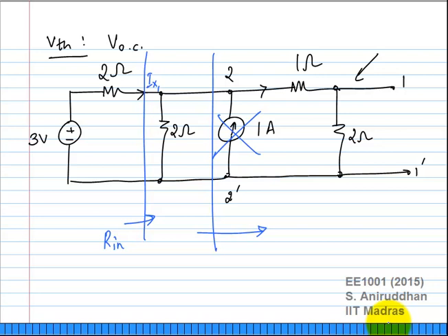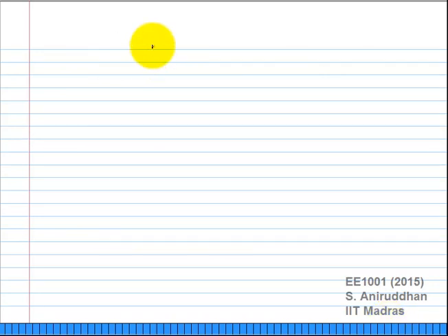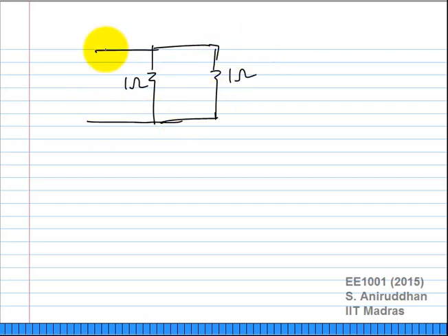Okay, what happens when a known current tries to enter a parallel combination of resistances, right? How would you know how much current flows in each one? So if I tell you I have a known current, let's say 1 ampere, entering a parallel combination of 2 1 ohm resistances. What is the current through each one? Half, right? So I have 0.5 amperes through each. What if I told you one of these was 2 ohms?